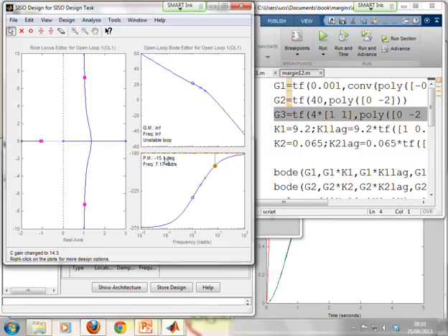I've stopped at minus 15 because, of course, to make the phase margin even smaller, I need more gain, and there's a limit to how much gain I can get. So let's look at the numbers we've got. We've got a frequency, I'll call it 7.2 for simplicity. I've said I want a phase lift of 55, which gives me a beta of 10. So remember those two numbers, 7.2 and a beta of 10.